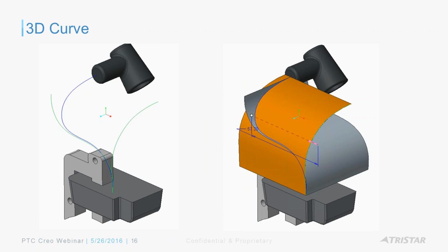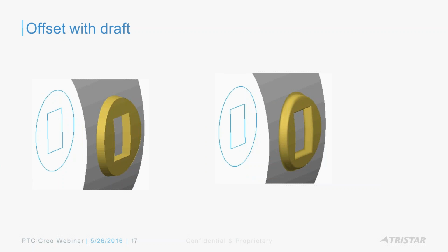So, pretty nice tool. I have these two curves here, this curve and this green curve that you see. Those are two 2D curves, and I'm just going to say intersect, and it gives you the resulting compound curve. Behind the scenes, the software is essentially creating a quilt, extruding the quilt, and then giving you the intersection 3D curve. You don't see the feature there, but that's what is happening behind the scenes.